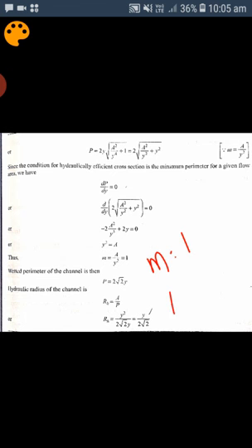So m equal to 1 means tan theta equal to 1, which means theta is 45 degrees, since tan 45 equals 1. The wetted perimeter of the channel will be P equal to 2 root 2 y. Then the hydraulic radius of the channel is R equal to A by P. Again you will get it in terms of y, that is, depth of flow.